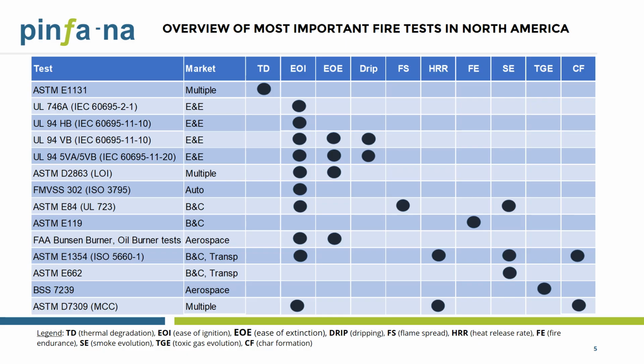It should be noted that there is no so-called best FR test method, since they are all application related, with different fire severity, sample size, orientation, and a different way of measurement. So passing one test doesn't mean passing another. However, some correlations may be established between a certain lab scale test and a large fire test to provide a prediction capability of large fire test performance of material. We'll briefly discuss that close to the end of this presentation.